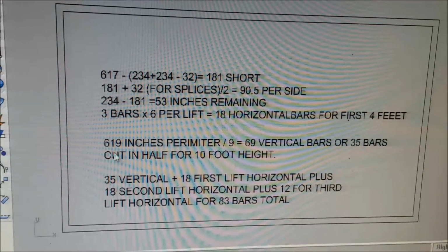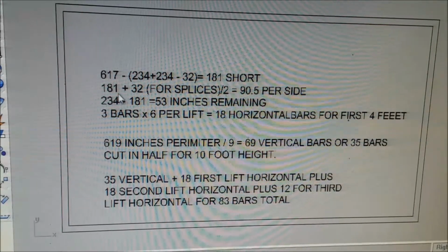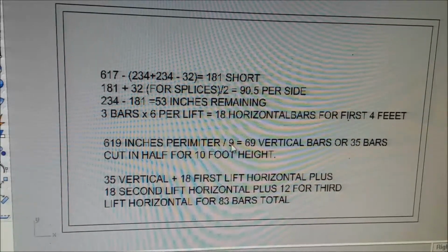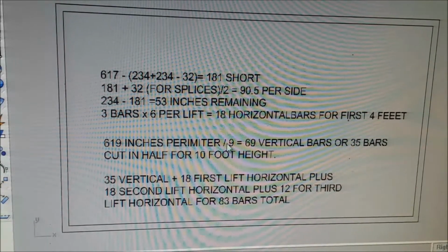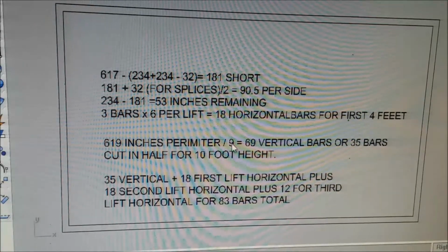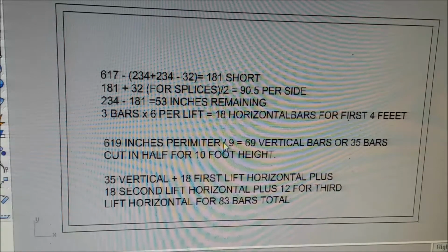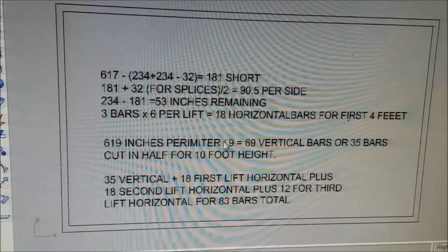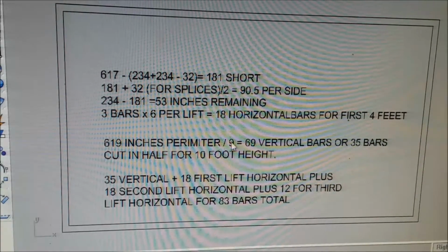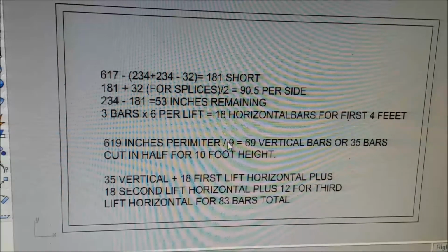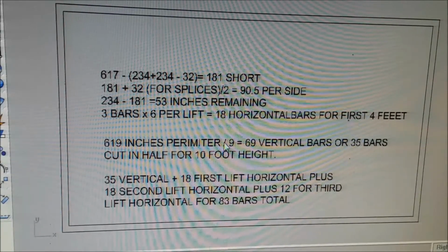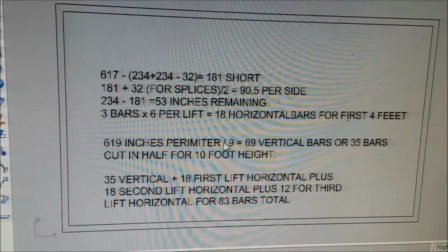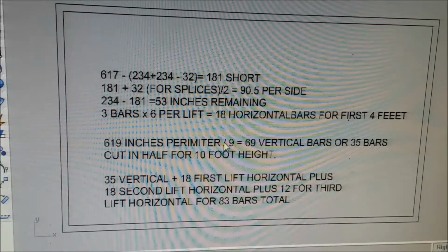Okay, now the perimeter, that's why I was confused, these numbers are the same. You've got the perimeter, we're going to put the bars 9 inches on center. We happen to have a notch board 9 inches on center. But I'm not too lazy to put new notches on the other side of the board, or you can do a 3rd set of notches on the face of the board. You can't put it on 4 sides, the board's too weak, it'll break. Because you're going to wrestle these things out from under the rebar. On walls, you just pick them up and carry them away, but on floors and stuff, you have to pull the wood out because you can't pick up that whole grid and carry it away.